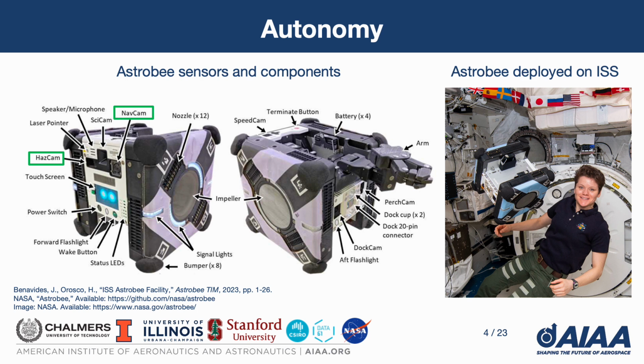In this work, the HazCam and NavCam were the two main sensors used. The HazCam is a picoflex time-of-flight depth sensor from which we collected point clouds, and the NavCam is a wide field-of-view color camera used for localization and map reconstruction.